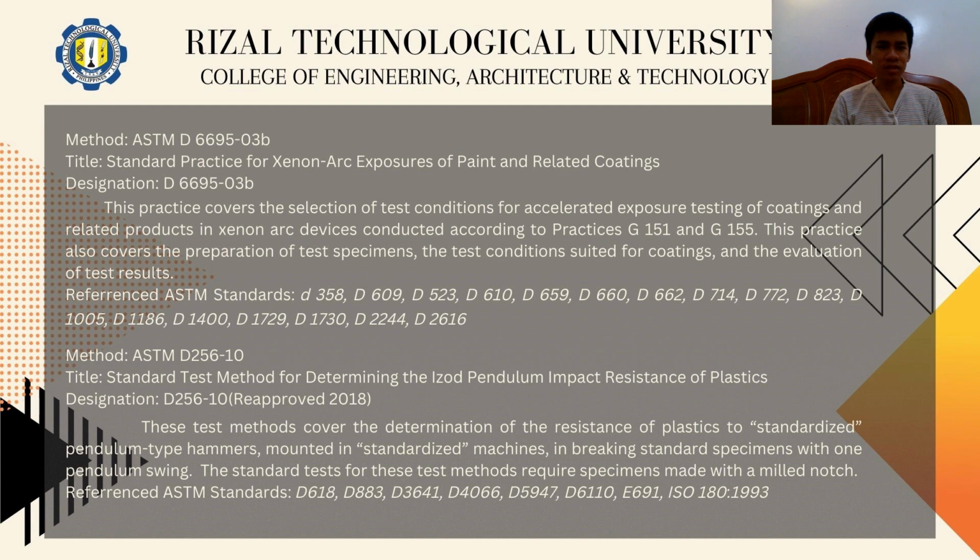Next is ASTM D6695-03b, Standard Practice for Xenon Arc Exposure of Paint and Related Coatings. This practice covers the selection of test conditions for accelerated exposure testing of coatings and related products in xenon arc devices conducted according to practices G151 and G155.